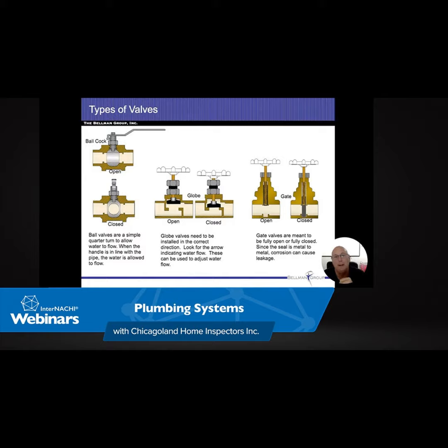Short cycling, I kind of mentioned this earlier. Water is not compressible. We can increase the pressure on it, but we can't compress it. We can only compress air. And so as we fill the tank up with water, we have to have some air inside the tank as well, so that we can maintain that pressure.